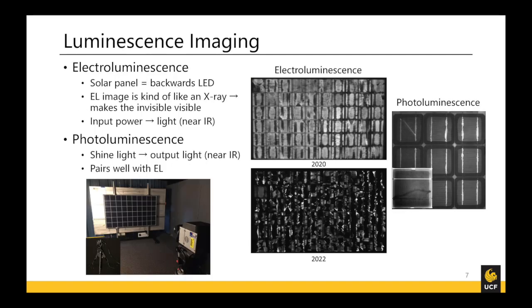So moving on to luminescence imaging. A solar panel is just an LED backwards. You can put light in, get power out. We can put power in and get light out. It's just that light's in the near infrared, so we need special cameras to image it.